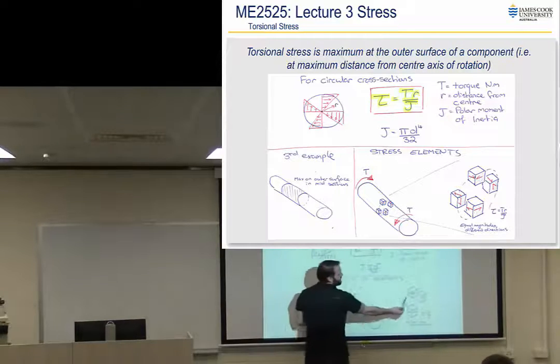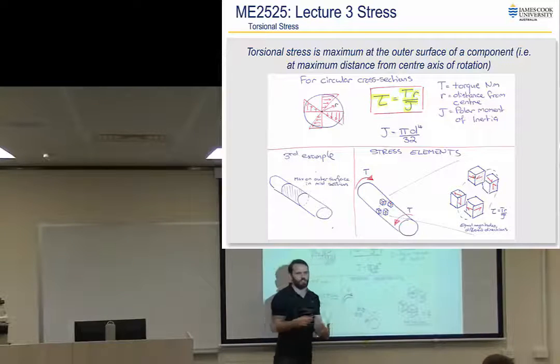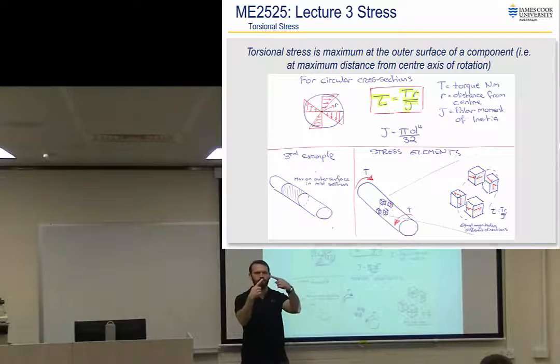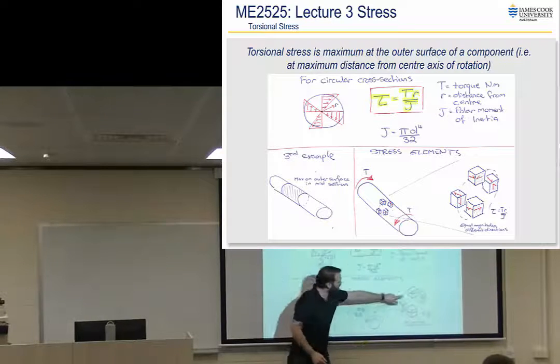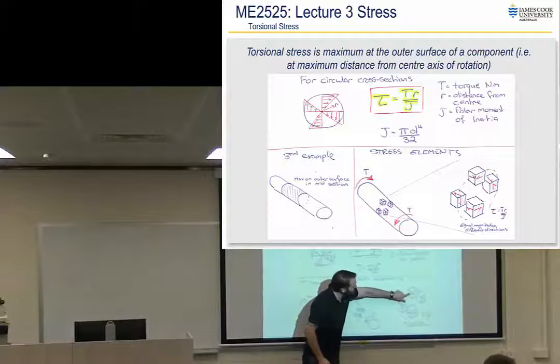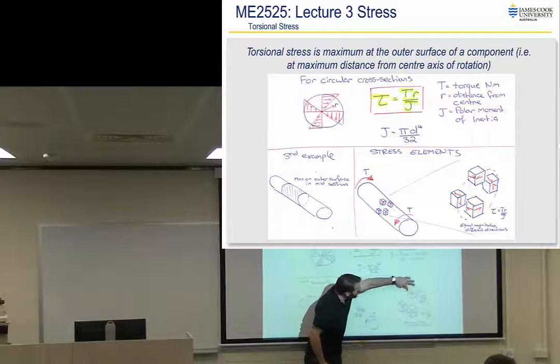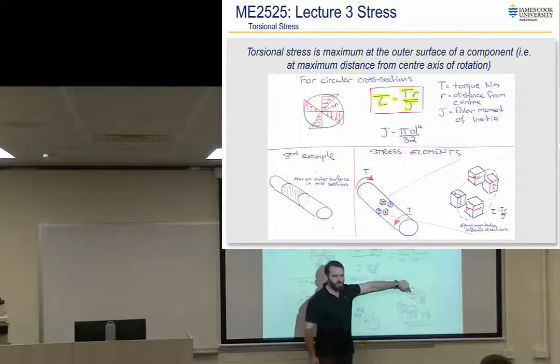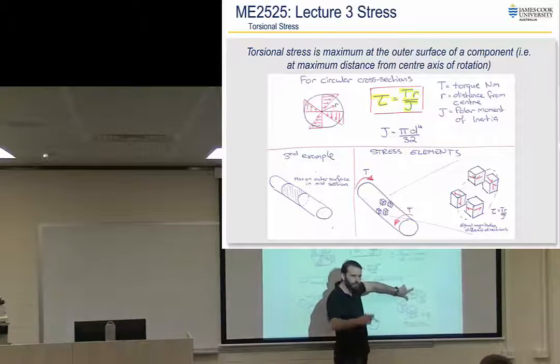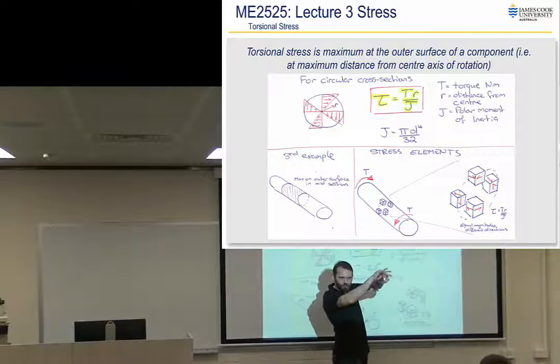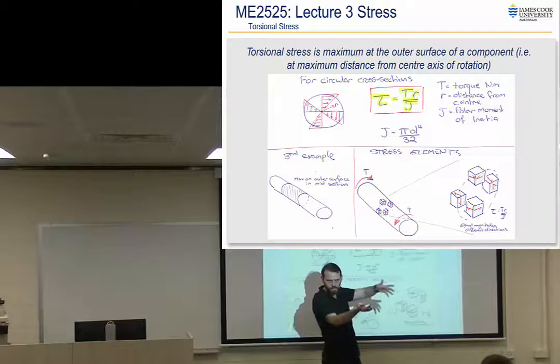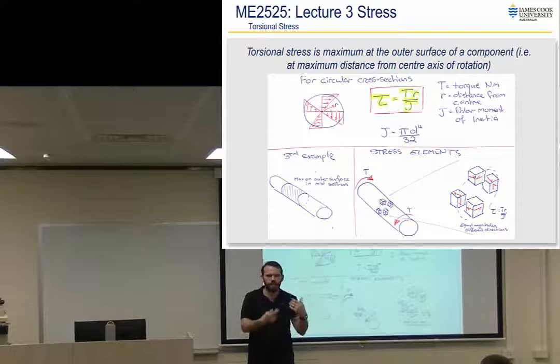Right? And so once we have the front face, we can get the other four faces that complement it, because we know that shear force or shear stress always points towards the same edge. So if I've got my front face there, I know the side face there points to that edge. I know the back face points in the opposite direction to that, because they have to have their tails at the same time. And just think about that back face for a second. Excuse me, that's pointed that way now, which is exactly the same as the other opposite face of the one you were holding in your other hand as well. So we know full well that that's going to be that way.